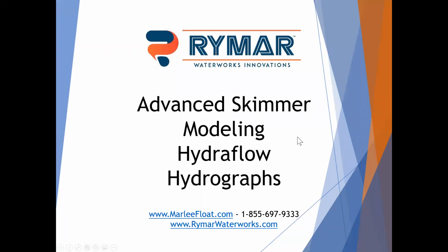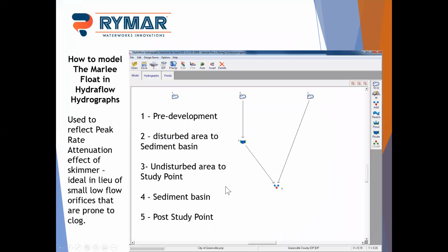So if you're going to use a skimmer permanently, you have to understand how to model that in Hydraflow or HydroCAD or whatever hydrology program you're going to use for your pre versus post calculations. So we're going to run through a quick example of a relatively simple site on how to model a skimmer in Hydraflow.